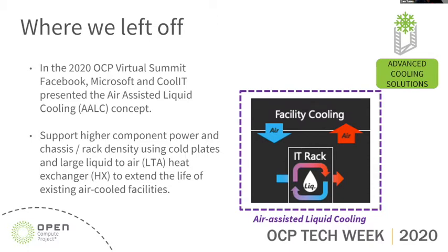OCP community. The concept of AALC is to utilize the superior heat transfer characteristics of liquid cooling to grab the heat right at the source, capture that energy in liquid, and transfer it to a large liquid to air heat exchanger. In this scenario, cold plates can support a higher component power in less U space as compared to traditional air heat sinks, which in turn enables higher power servers, which then rolls up into higher power, higher rack densities.